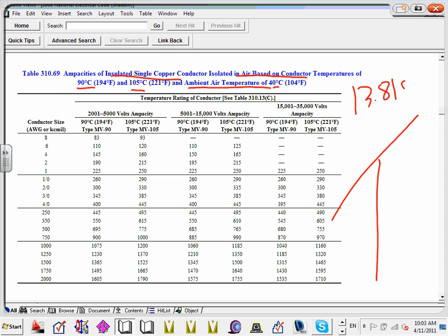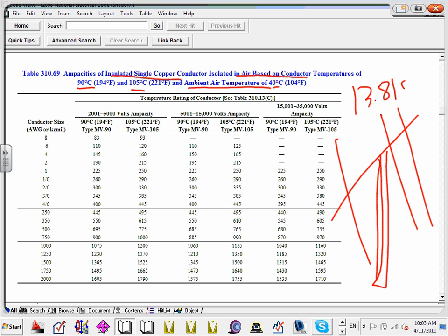Here are my conductors, sitting 1, 2, 3 conductors, and this is my pole sitting here. And my conductors were 4-aught. If I pull them and the insulation is medium voltage, 105, look how much current they can carry if I use this insulation, 445. Spencer, do you remember how much 4-aught can carry? 230. Look how much this can carry, 445. Are you kidding me?